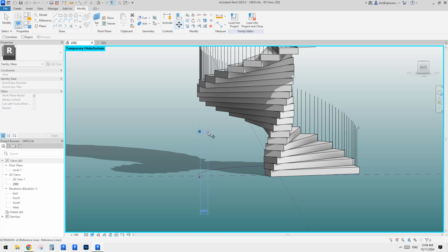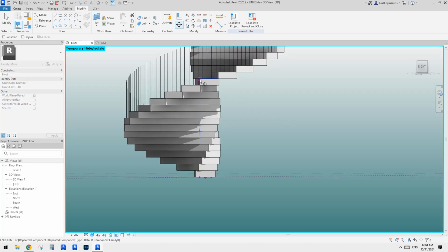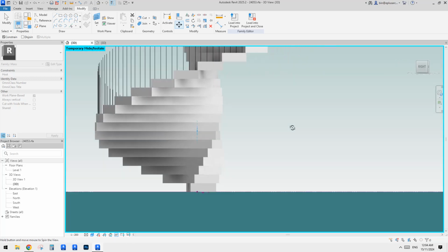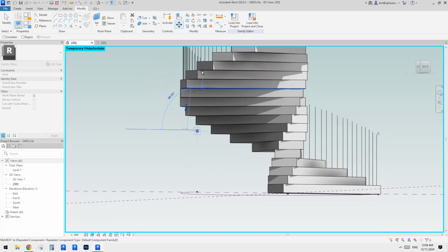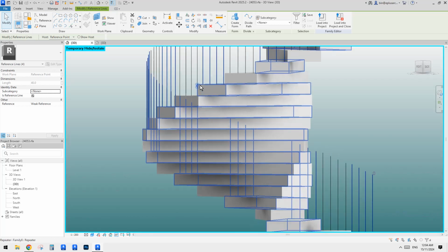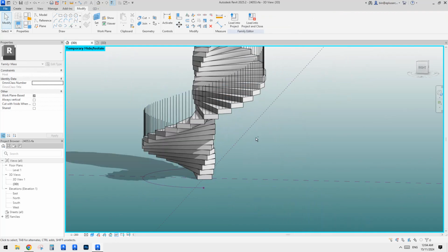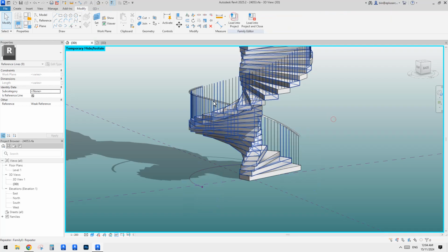Okay, so on this end, but we still need to move this up. So MV, this time I think I will probably use this one, right? First I want to match that point, that step height, roughly this one. So just need to remember that's that one. Then I'll just move it up by 1 meter. Okay, so roughly, yes, roughly there. Then we can select this profile together, control select this and control select this.